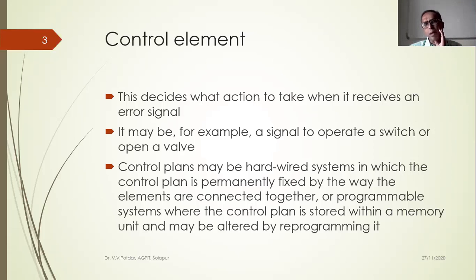So the control action can be instantaneous, based on my present requirement. The control action that I want is to have the heater output which is proportional to the error. So I need to have some proportional controller in the control element so that the error is amplified, and if the error is positive, in proportion to that positive error, my controller should generate a proportionate output control signal.